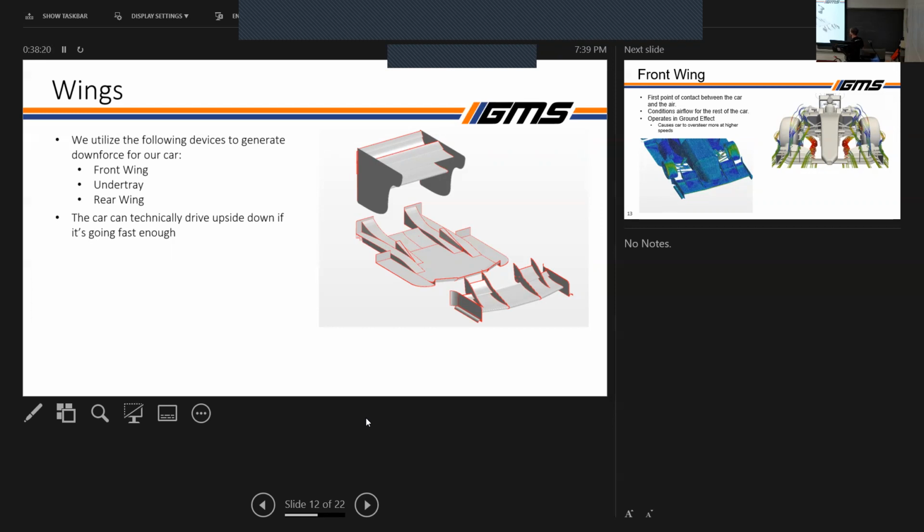It also decreases the downforce slightly, but that was done to balance the center of pressure and bring it to where we wanted it, about 56% rearward. Granted, that's based on some old data, and we're currently trying to ascertain it, but that's where we're trying to put it for now.